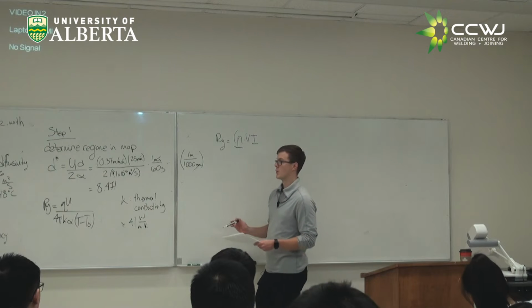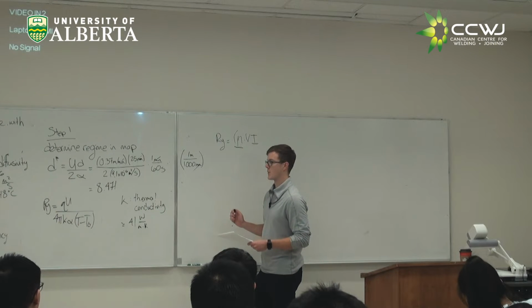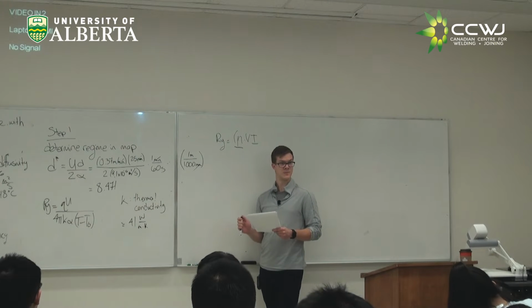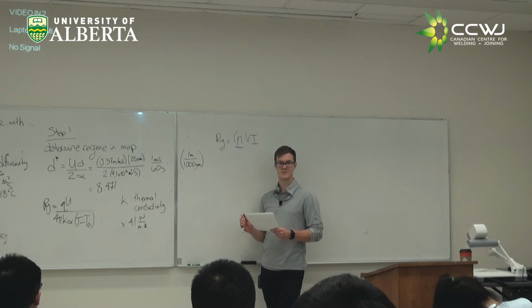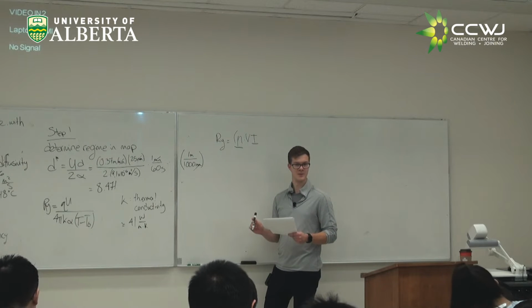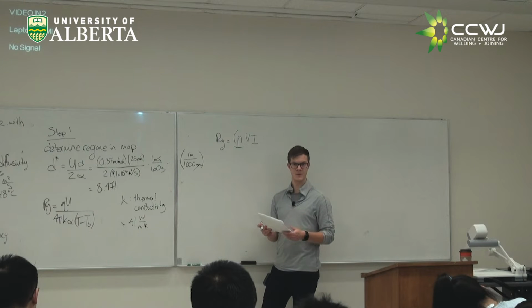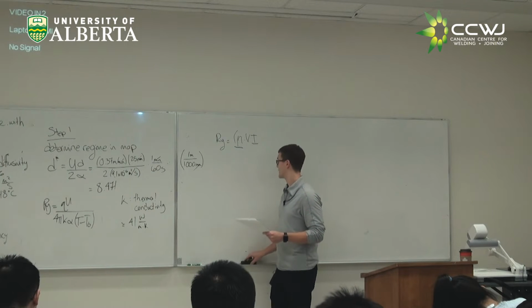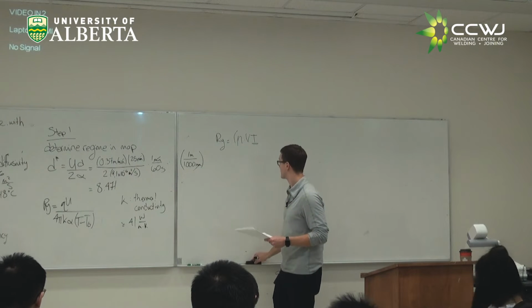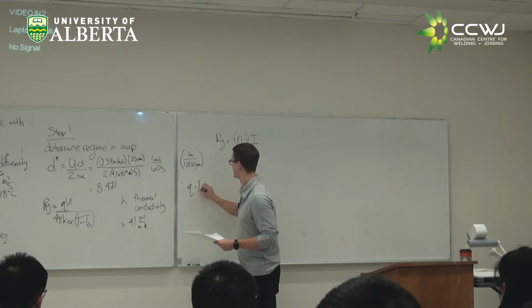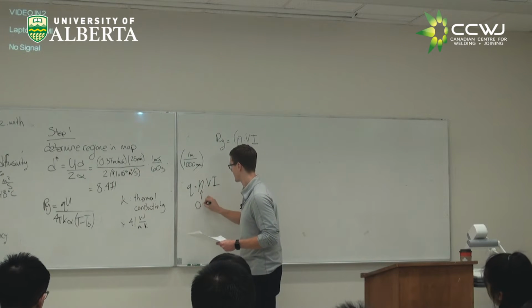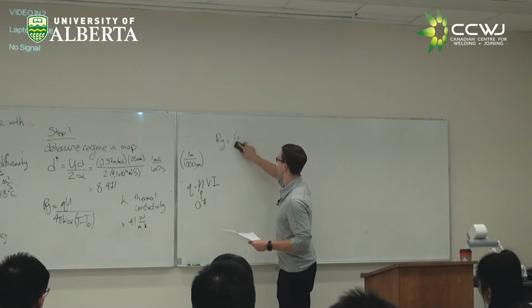It says we want to use an approximate thermal efficiency for an argon CO2 blend. So what would that be for GMAW? This should be in the notes from today. 0.7? Yeah, that sounds good to me.